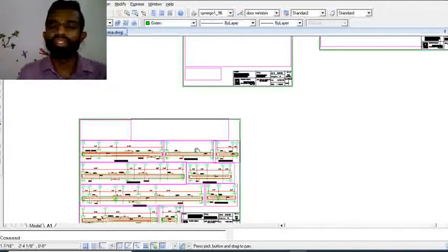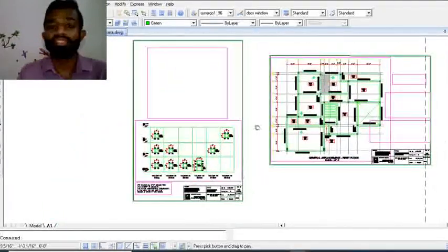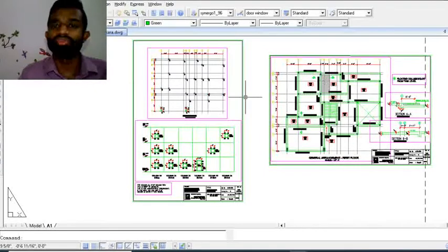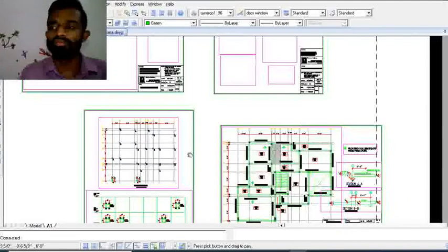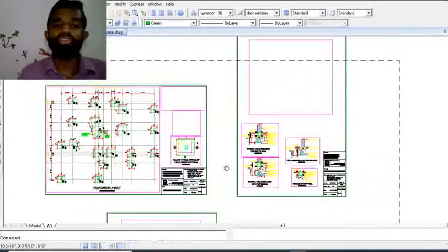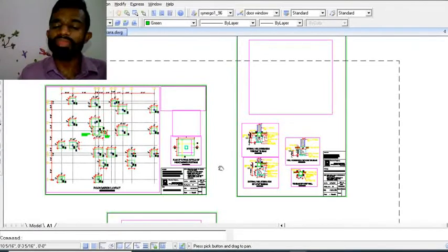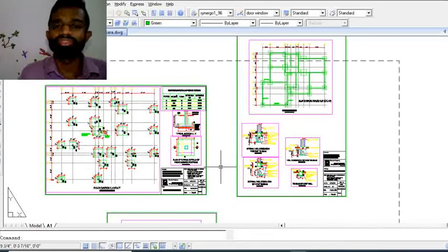So usually, when loading the slabs, structural engineers use two types of loads, the dead loads and the live loads. Dead loads are the self weight of the slab, and when you do finishes or lay the tiles, the tile weights, and if you put brick walls or something, the brick loads. All the dead weights, self weight, brick loads, finishes loads, are taken as dead load.